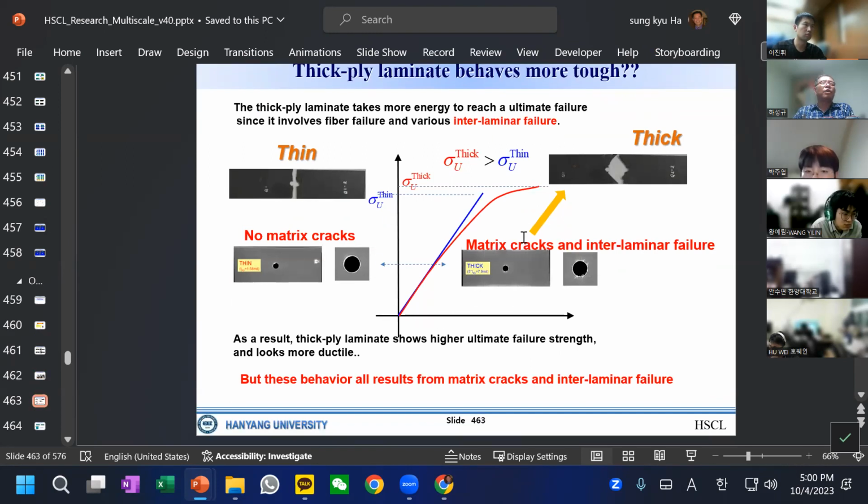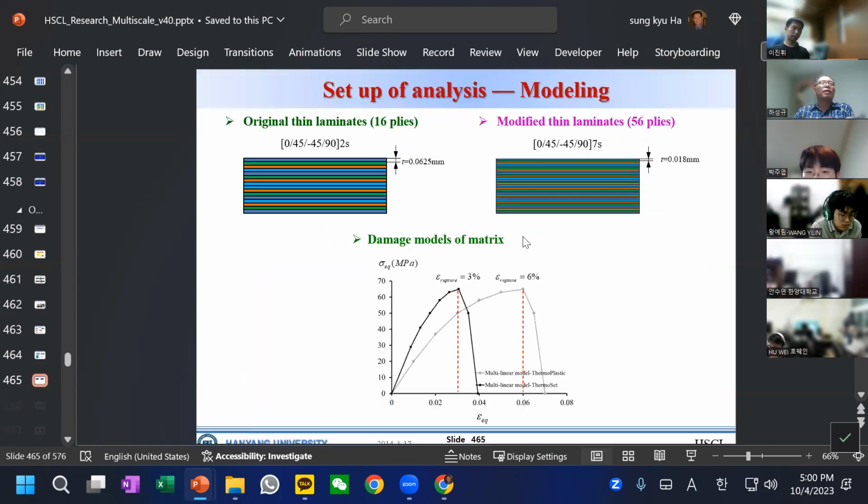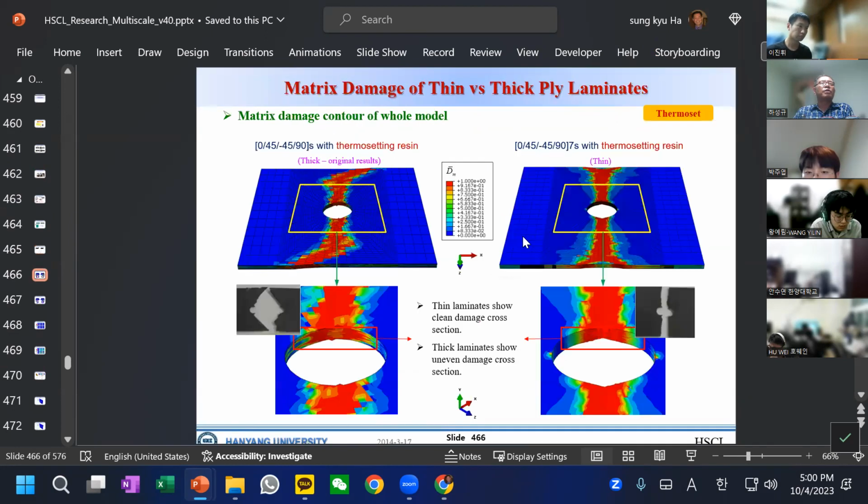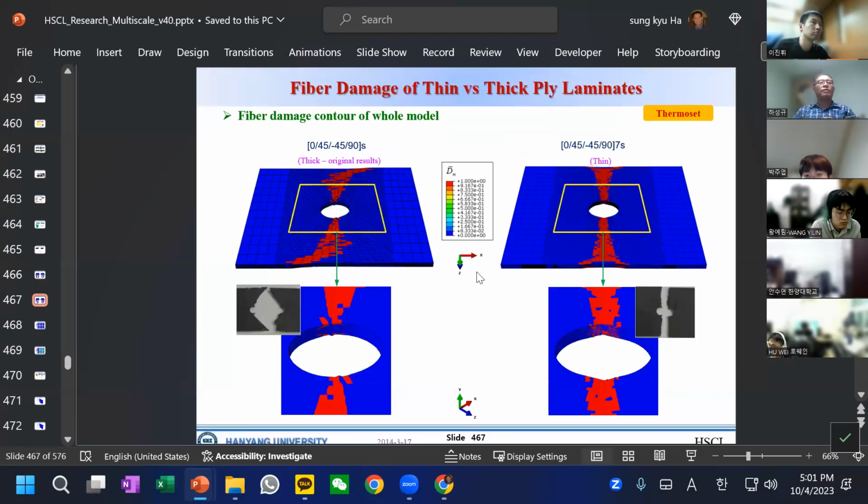Now we are able to understand it by simulation. It's a complicated procedure, and I don't want to go through that. But as you can see, through micromechanical failure analysis, we understand how this can be a plus minus 45 failure, and how this one can be a very brittle, 90-degree failure.